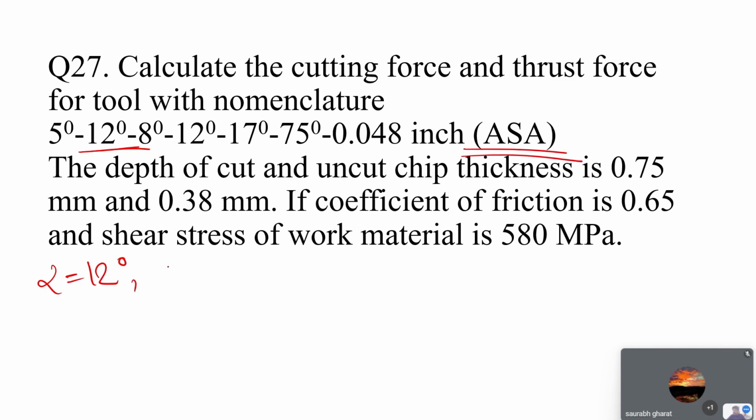We have d, the depth of cut, 0.75 millimeter. We have the uncut thickness t1, 0.38 millimeter.